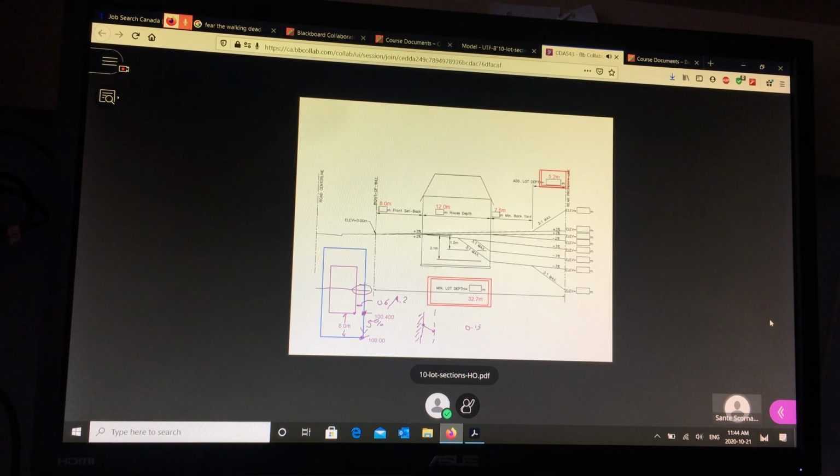There'll be another house next to it, and you would go up to that one as well. This height is at least 6 inches or 15 centimeters, and then you're creating a swale, like a ditch, between the houses. So if the elevation here is 100.4, what's the elevation here going to be?